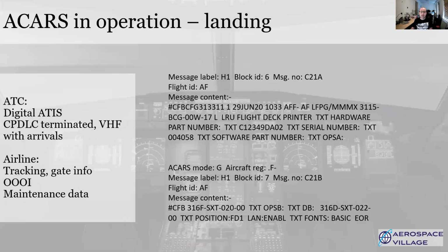Just prior to landing, the aircraft will obtain ATIS data, Automatic Terminal Information Service, which gives data on the runway in use, temperature, surface wind, and so on. Traditionally, this has been an audio broadcast, but by using ACARS, this data can be obtained earlier and help the crew prepare for the right runway in use. CPDLC is not used when immediate responses might be needed. Remember, it has a maximum of 30 seconds latency. So this is ended with arrivals and the airport controller taking over via VHF voice.